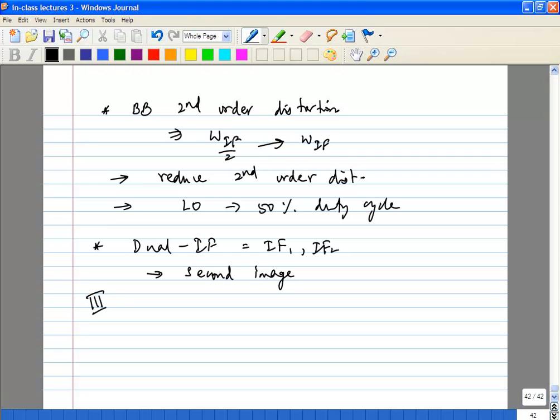Okay, now let's look at image reject receivers. Okay, so the main motivation is that image reject filters can't be implemented on chip, so they have to go off chip for good filtering. Again, you have to drive 50 ohms and so on. So that has motivated people to come up with architectures where you don't use a separate filter, and you try to cancel the image separately. Okay.